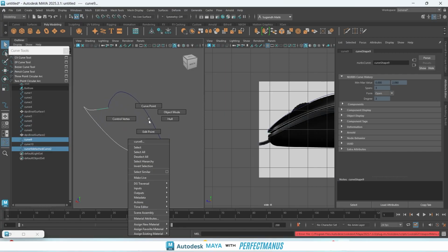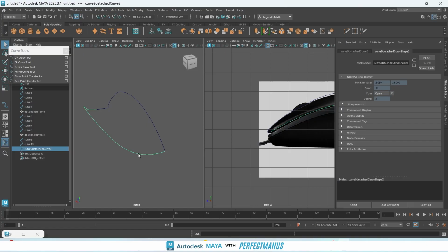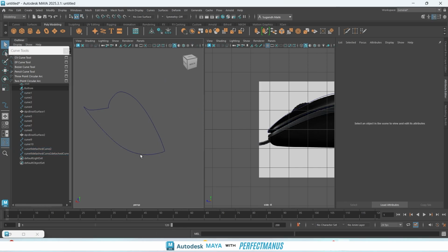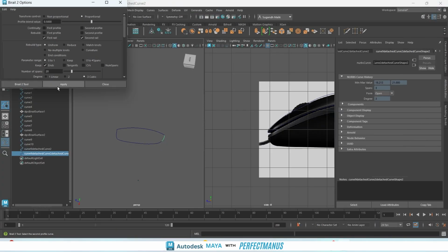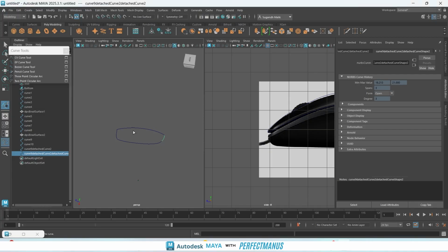Similarly from the back part, with the curve point, select a point. Okay. Either this one I guess or this one, totally depends on you. Okay, and go in the curves and detach. Okay, from here now you have the four sides. You need to make sure that they have equal spans. Okay, it has three and it has three spans, so you don't need to again create these. Now going on to this one, applying it, this one, this one, and this one.